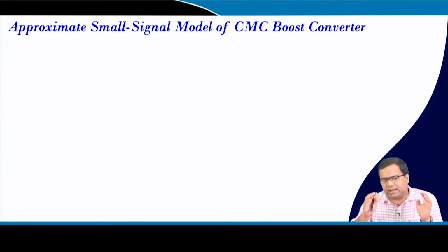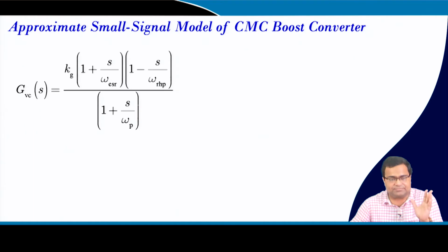We will start with, in fact, in the previous lecture for a buck converter, we found that a first order model is sufficient if you do not consider any ramp compensation, or if there is no subharmonic oscillation. But in case of ramp compensation and subharmonic, it is better to use a discrete time model. Otherwise, the design that I am going to consider has a duty ratio of less than 0.5, where the first order model will work perfectly fine up to a certain bandwidth, that means crossover frequency.